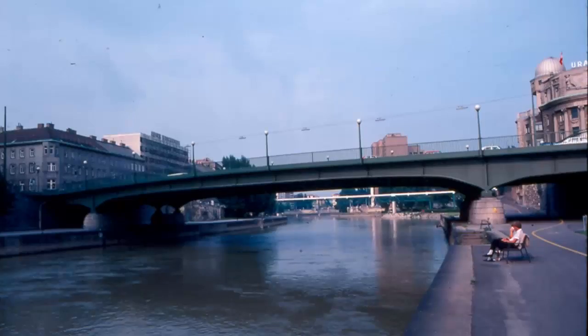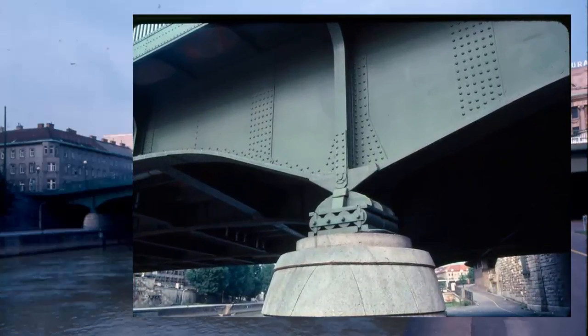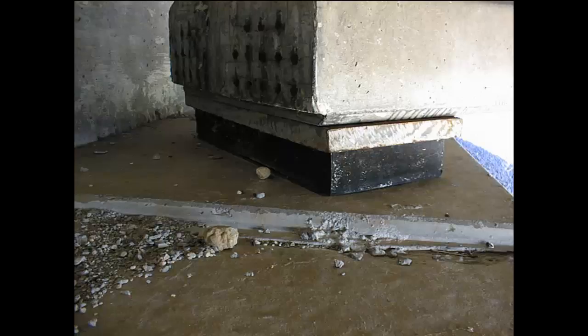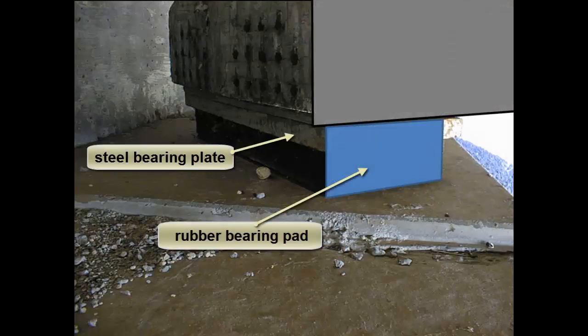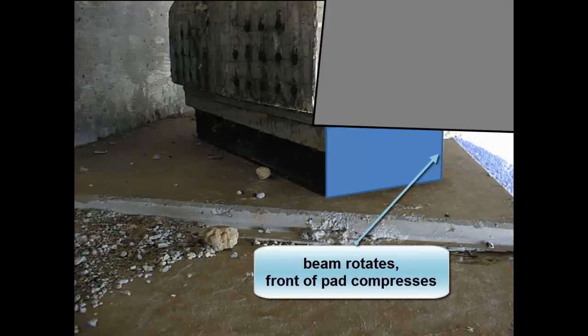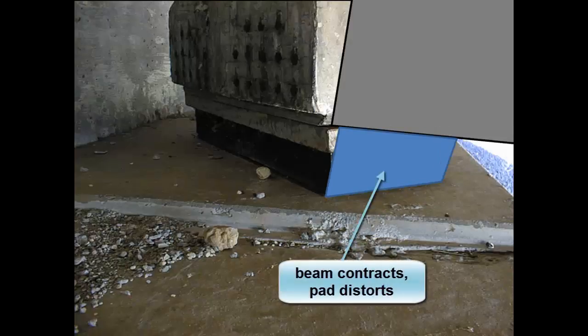This bridge in Vienna has a large roller to withstand heavy weights and large movement. Rollers are not always created by actually putting rollers into the structure. This bridge over U.S. Highway 151 has concrete girders that sit on rubber-like bearing pads instead of rollers. When the girders contract in length during winter, the pads deform, acting like rollers.